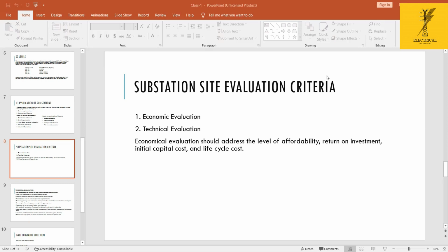We are designing the earthing for both. Suppose for 33 by 220 kV, I can find how much equipment will come in 33 kV: the lightning arrestor and so on. I already prepared a table in Excel. In that, for the lightning arrestor, what are the flats to be laid? 100 into 16 mm, 50 into 8, and 75 into 12 for 220 kV. For the breaker, what are the earthing points required and what is the length? And for the earth mat for the 33 by 220 kV system, 75 into 8, how many lines will come? By selecting the area and adding that formula, I get the total earth mat, and I calculate the weight of my total GI, galvanized iron flat.